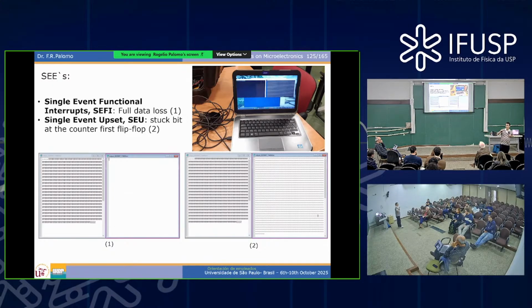Again, if the device were destroyed, it could be impossible to reconfigure it again. But after the single event functional interrupt, we stopped the beam and reconfigured the whole design, and the device started to work perfectly. There were recoverable bit flips, because the devices are still working. There were no stuck bits. They are still working in my office, after considering a cooling time to avoid radioactivity in my office.